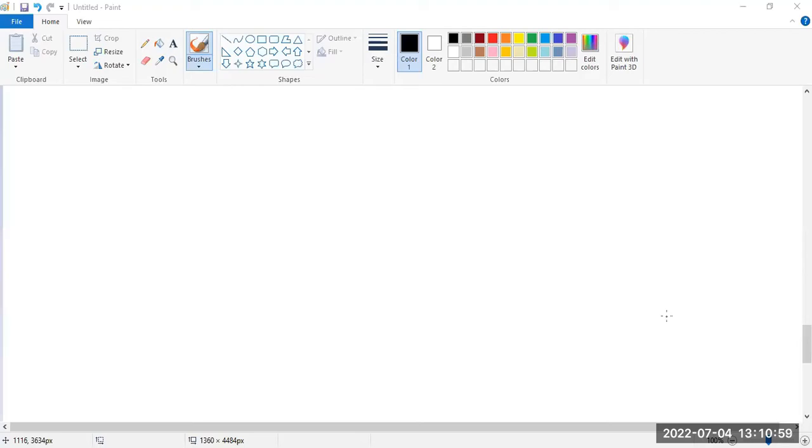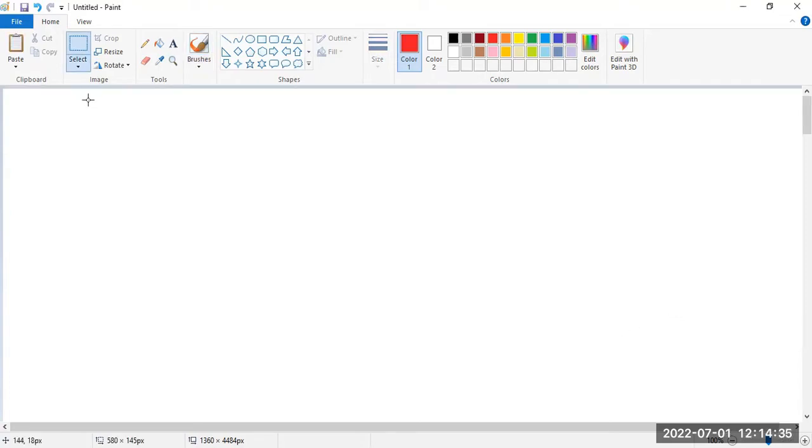In this video, I am going to explain the concept of Nyquist plot in detail. First of all, let us see what is meant by Nyquist plot. Nyquist plot is a plot which is drawn in F(s) plane or G(s)H(s) plane corresponding to the Nyquist contour which is in s plane.